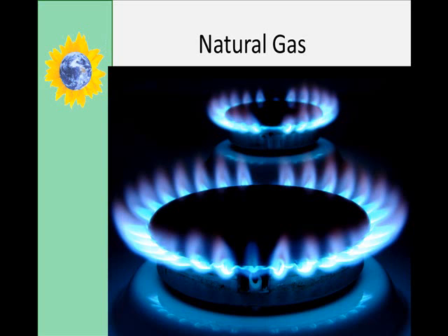Electrical generation by natural gas has been improved by the development of combined cycle systems. These systems put together a natural gas-fueled combination turbine with a heat recovery steam generator and a steam turbine to produce electricity in 2 ways rather than just one. The result is that roughly 60% of the heat from the natural gas is harnessed to make electricity, creating a more energy-efficient system.